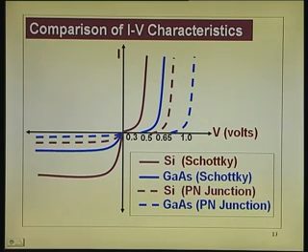If the solar spectrum falls on the PN junction, and you put a multimeter or a voltmeter across it, you will see a voltage developed. If you take silicon, it will be less than the cut-in voltage, less than the built-in potential. So, if you get about 0.55, 0.6, you will hit the roof with joy.